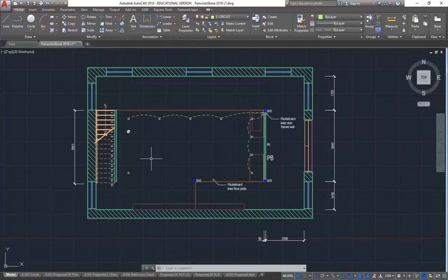Not even on our dimensions? No, don't dimension. It's actually bad practice because those things need to be fine-tuned and worked out properly on site, and the electricians know how to do that. So it's not a good idea to dimension. I know sometimes people, because they want their design to be followed, will dimension the lighting spacing, but generally you don't need to. It's fairly clear because the walls and everything else will be drawn and built with exact measurements, and then the electricians can set out within those new walls and ceilings that have been constructed, and work around the structure.